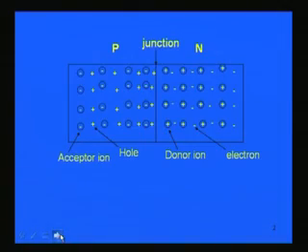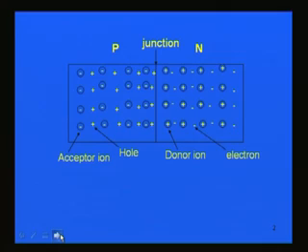When you have p and n type of semiconductors combined together by some appropriate scheme like ion implantation or diffusion, this process is not mechanical, mind it, so as not to disturb the crystalline structure of the silicon or germanium semiconductor, which is the base material. A properly formed p-n junction will have p-type on one side and n-type on the other side.